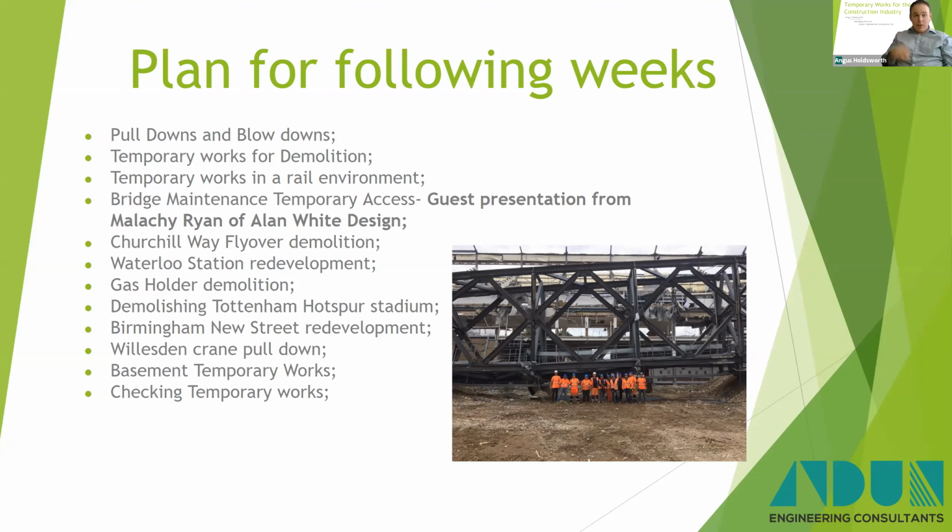So if you're looking at temporary works, the yellow temporary works book, you'll see within there, there's a chapter I've written on temporary works for demolition, and it talks about scaffolds. Where they are to be used, you've got to make sure that tubes aren't projecting into the structure. That's one key issue. And you've got to make sure that the scaffold is designed to cantilever at least one lift past the level of the structure you're demolishing, because those are two cases that are commonly missed with scaffold designs.